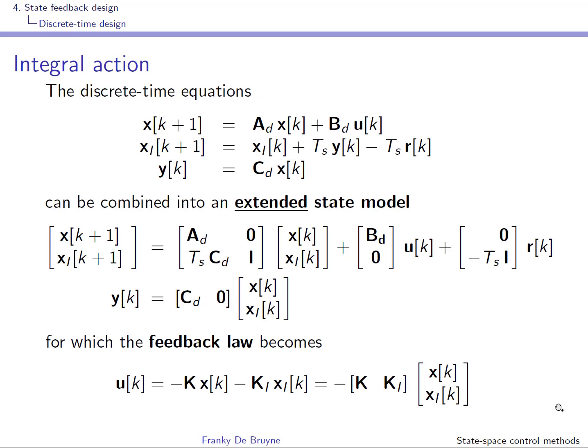So you can of course implement integral action also in discrete time, and as before we have to construct an extended state model in which we are going to construct an extended state X of E. Well, the first part will be the state of the original system, and the other part of the state will be the states associated to the integral action.